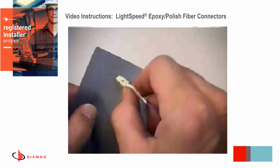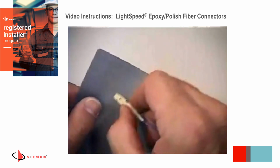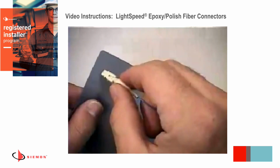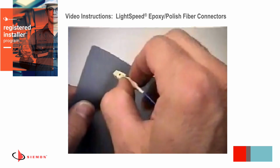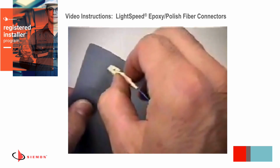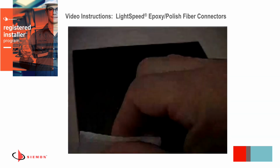Using the gray 12-micron film, perform an air polish. Gently brush the ferrule tip against the dull side of the polishing film in a figure 8 fashion to wear the small fiber protrusion into a smoother, more polishable tip. Continue until the tip is almost flush with the ferrule. The number of revolutions will vary dependent upon the length of the fiber stub left after cleaving.